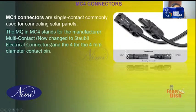This is the name of the company which manufactures the MC4 connector. The company's name is Multi-Contact. So this is the MC term. The name MC indicates multi contact. Now the name is also changed. It is changed to Stäubli Electrical Connectors. Stäubli Electrical Connectors. And 4 indicates the diameter of the contact pin. Depending upon that, MC6 is also there. 6 square millimeter wire is also there. So 4 or 6 indicates the diameter of the contact pin.